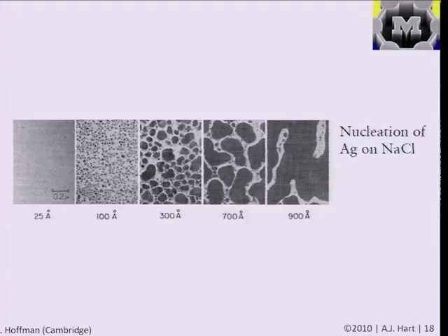And you can see with time, as more atoms hit the substrate, you end up depositing into larger clusters, and the clusters can also lose atoms to one another based on their own energetic stability and their own size, and you eventually get a film that is more or less continuous. And with time, you would evolve that grain structure in the film that would then be going from the size regime we're interested in to the size regime of continuous films.